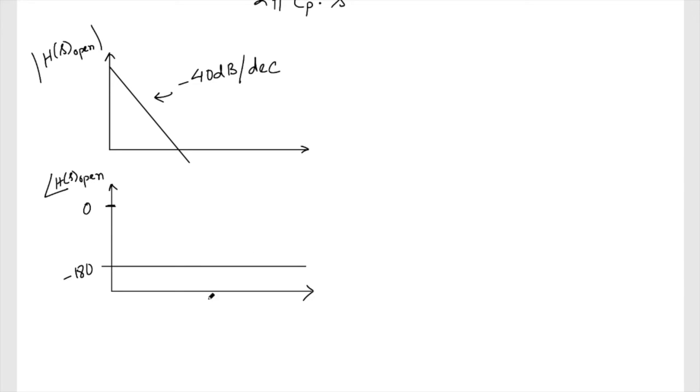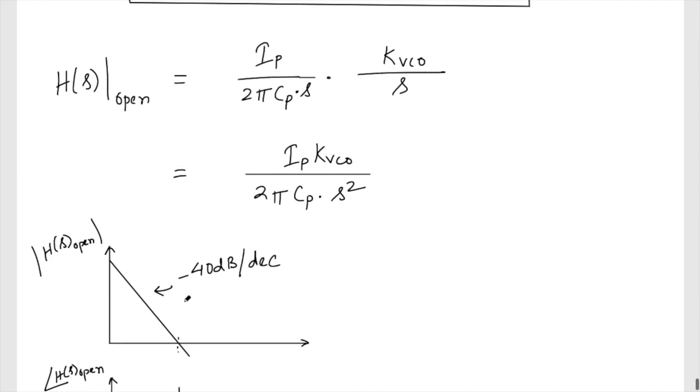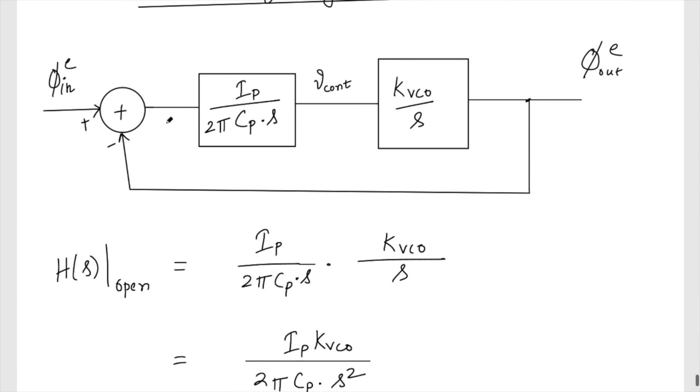Because of which, at this point we can see that at unity gain frequency there is a phase shift of 180 degree. So we have a negative feedback system, and the open loop transfer function of this one is shifting the phase by 180 degree.